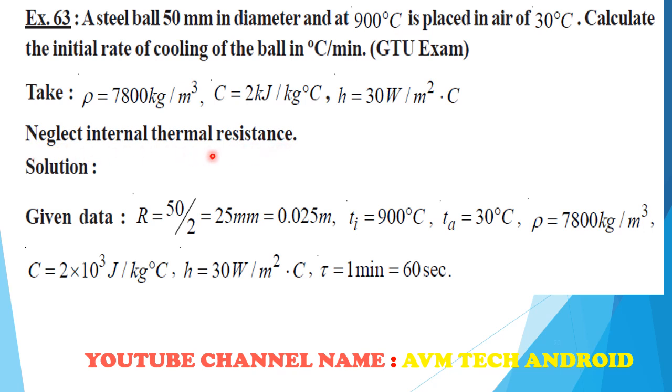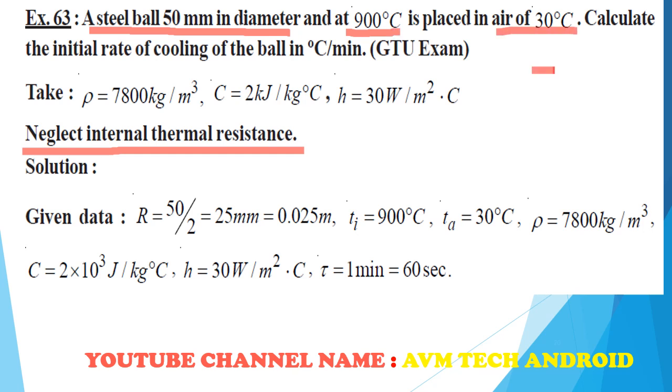When this is given in the data, we must immediately understand this is a problem related to unsteady state heat transfer. The ball which is at 900 degrees Celsius is placed into the air, so immediately when the time is more than 0, the temperature starts to vary. So this is a transient heat transfer.